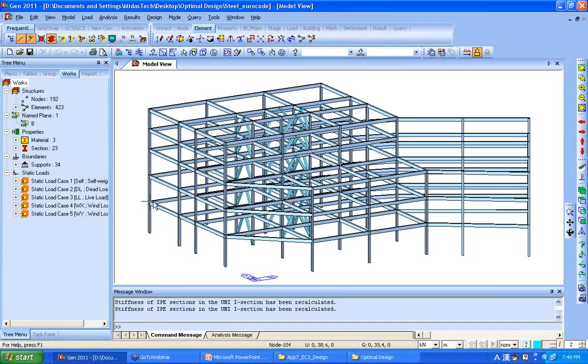Okay, this is also the 5-story building. And in order to find the optimal section, you can use the easy way, which is the optimal design function. By performing optimal design, you can see a variety of types of graphs as a result. If you want to perform the optimal design using the database in midas.gen or your own database, you can directly specify your desired section shape dimensions into the program. I will show you the optimal design. For the optimal design, I will use this model file as I mentioned.